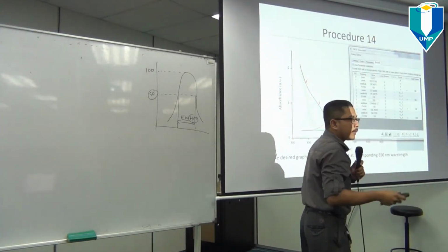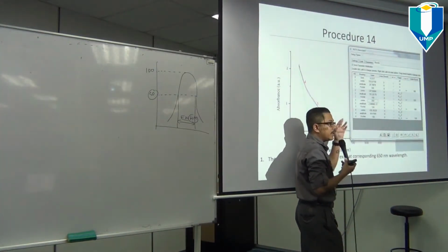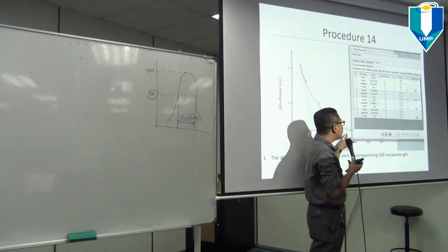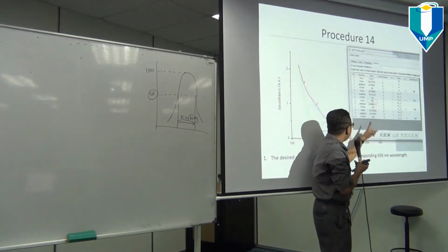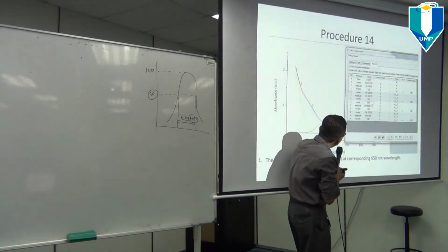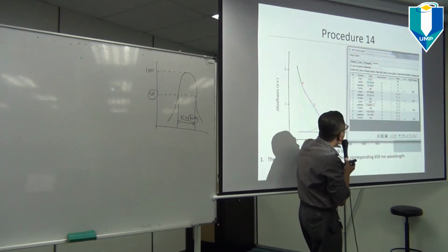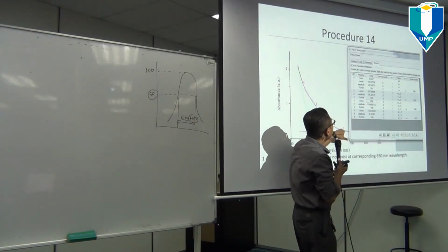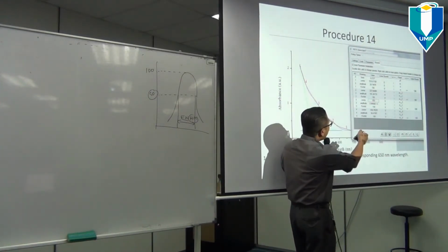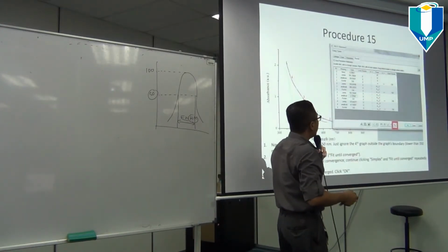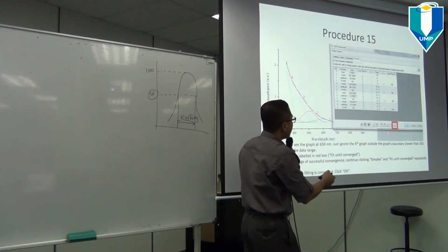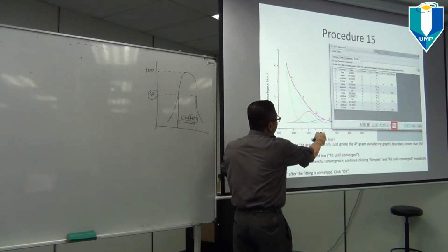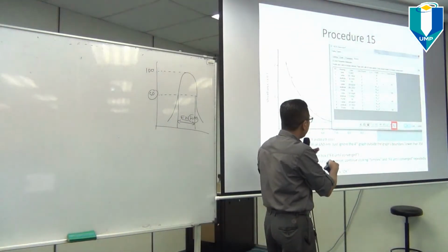They are okay already. So if it happens later, if you try with another data and the centers are correct, but you still cannot see any peak. See, it has 650. There should be one peak over here, but it doesn't show any peak at all. It happens because your amplitude is too small. Change it to 20 or 60 or 40, then you will see another Gaussian graph appear over here. So let's say I modify this one. I put 12 for example, and click the simplex button, then I will get this kind of graph. See how the purple and the black lines now coincide. So this fitting is acceptable.